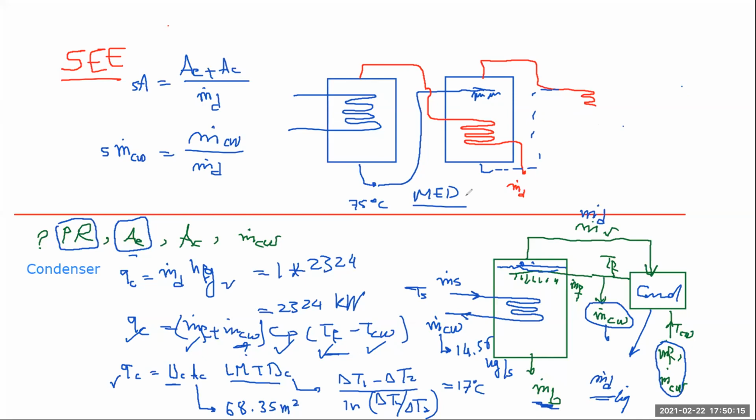So that you are not going to throw away high temperature fluid. Maybe the temperature which is leaving here is 75, so what will leave the next one is going to be 70, and what will leave the third one is going to be 65. Then you can continue doing that until you are rejecting energy at 40 degrees centigrade. And that's enough. If you put one more effect when you get in at a value of 40, that's not enough to evaporate an additional amount of vapor to be worth the investment of putting another unit with a tube bundle and so on. So typically, we use like 8 effects in a system like that, so that the last effect would have a temperature that is greater than the seawater temperature by a value of 10.